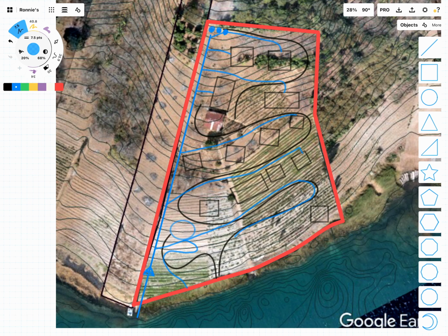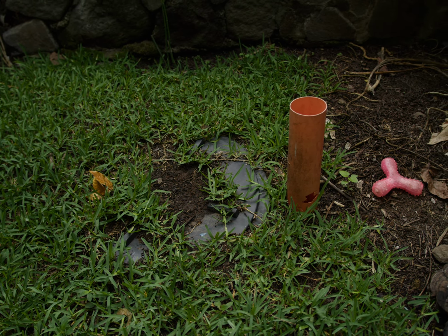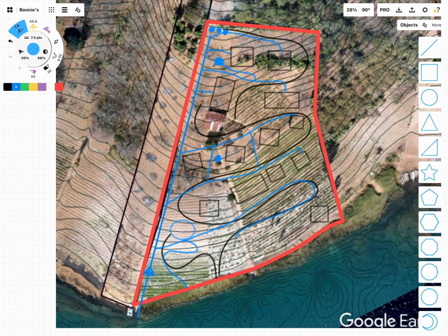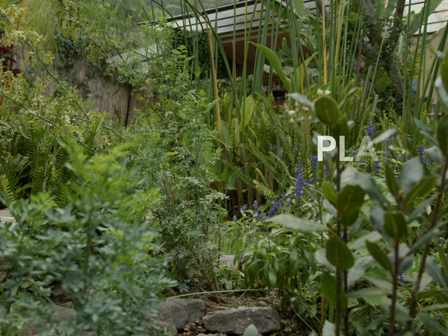Water runs back down across the slope, branching to each unit. Lines mostly follow the paths, except they cut straight across the switchbacks. After the houses, wastewater runs into biodigesters, then out through a French drain field into the ground. Not every unit needs its own. The glamping units share. Cluster a few houses to one tank.